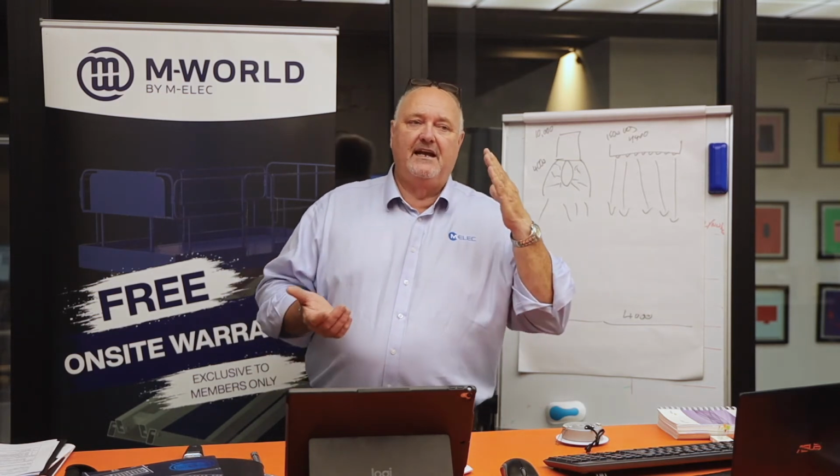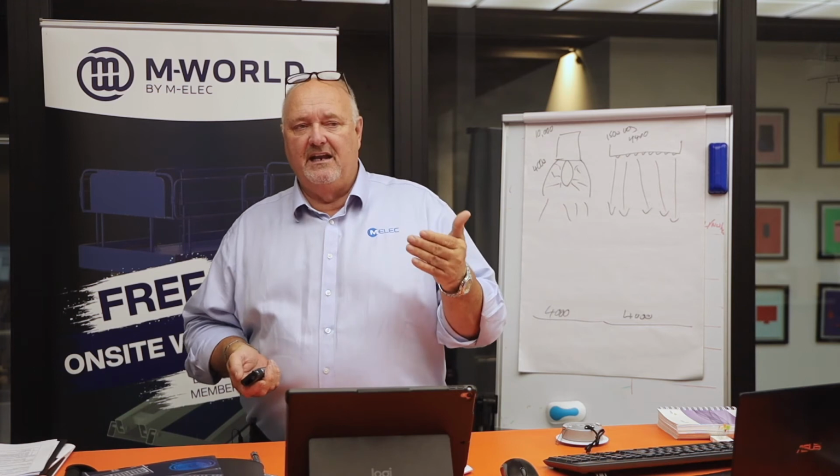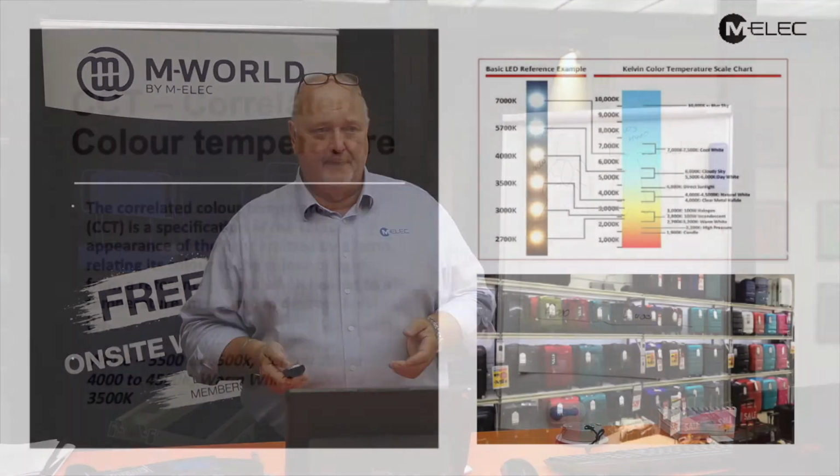So CRI is really important, but it is very situational. You have to consider your situation before you decide what CRI you want. If it's an office building, you want clear, crisp light, but you may still only need a CRI of 85 to 90. You don't have to push it to that top level, but that's more about flicker free and glare and things like that.